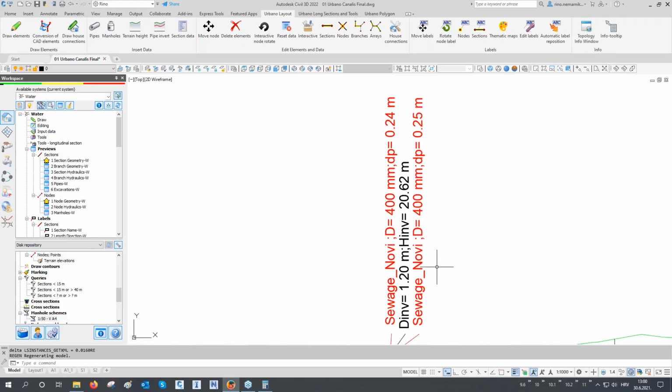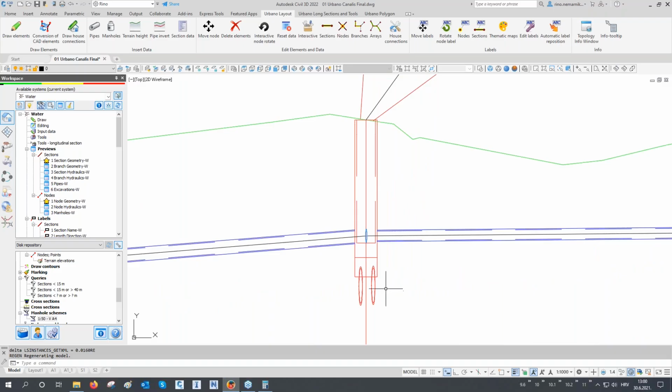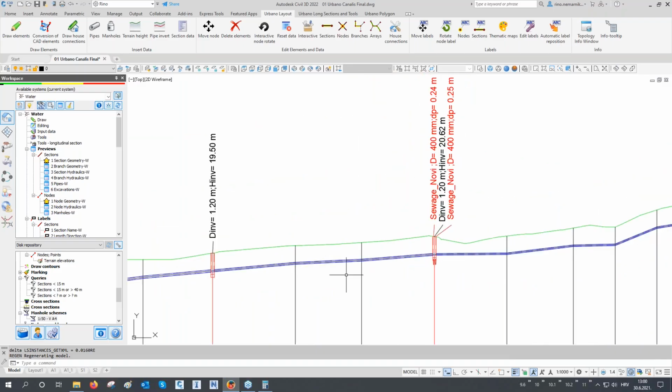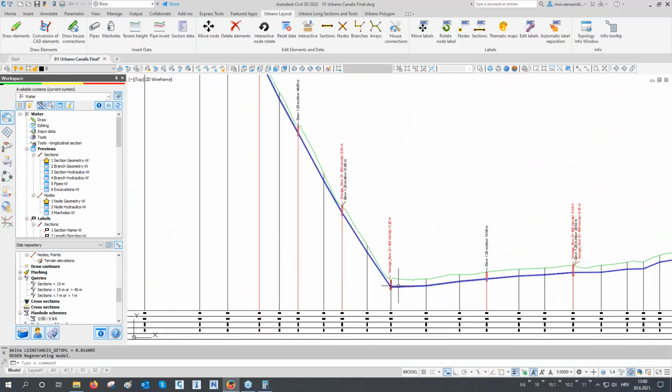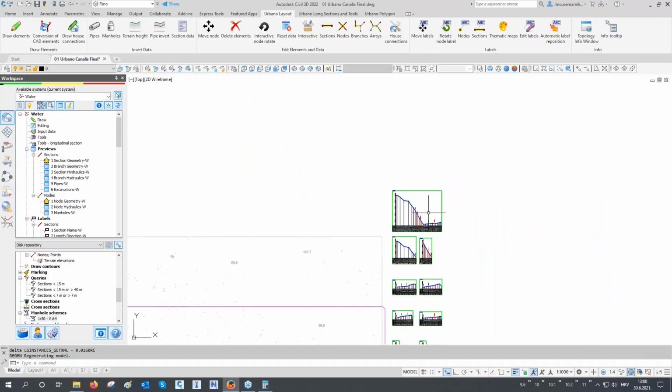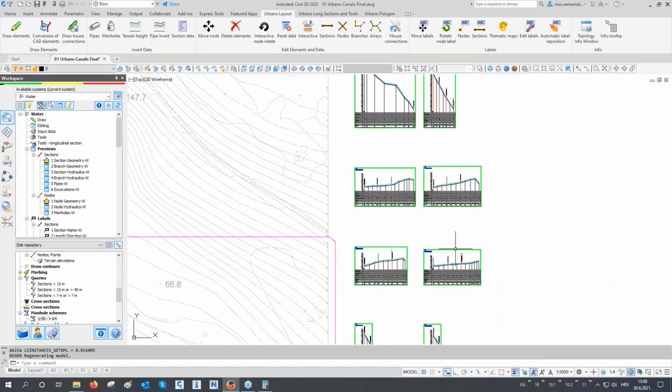And now we see that the program automatically computed and is showing this pipe crossings and pipe clashes. So you can see the distances between the pipes, but also graphically we see that we have a clash between pipes and manholes. You can see the relative position of the pipes, and this is for the water system that, let's say, one designer did.